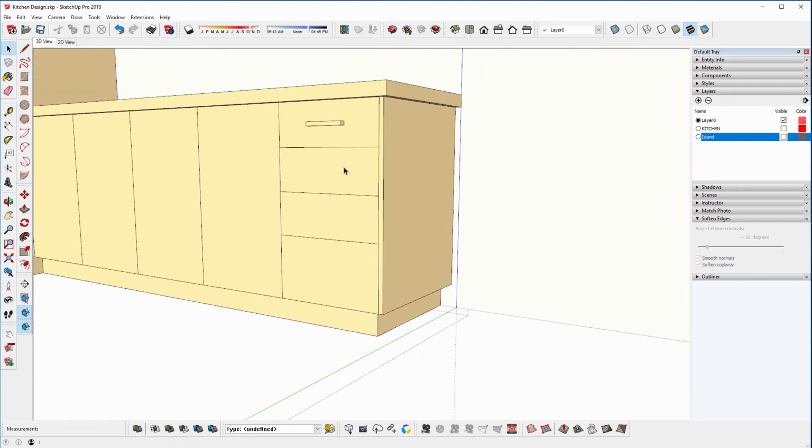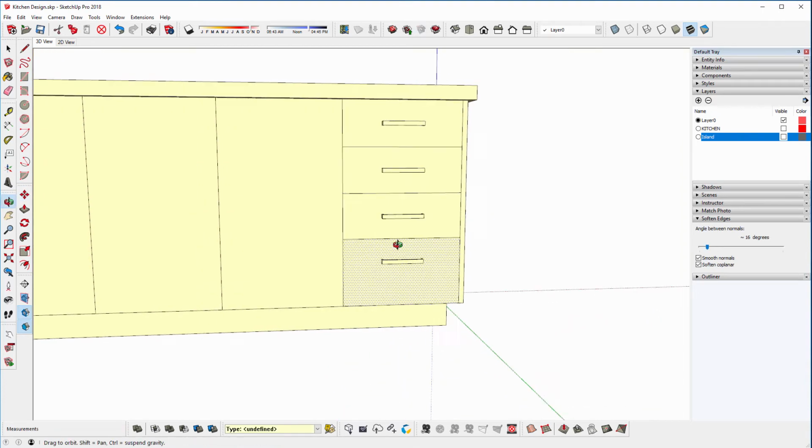So then we can get the select tool and select that, and then use the midpoints to copy that down. Once you've done one copy with the move tool and Control, click, you could then go 2x, enter, or sorry, I went 2 divide by accident, so 2x, enter, and not enough, 3x, enter. So you get the same distance and divisions going downward.